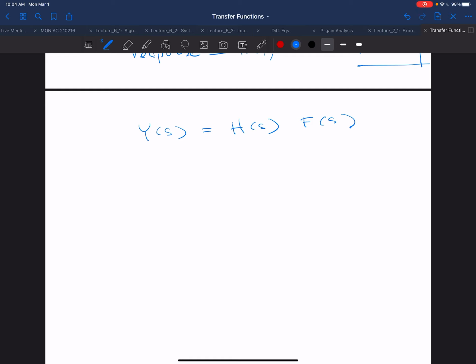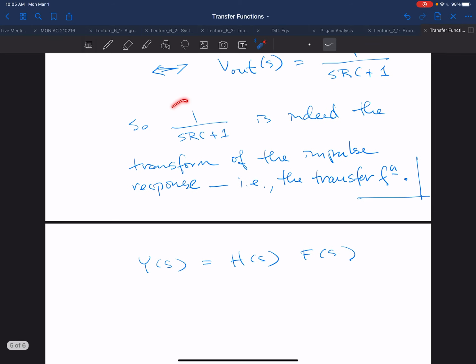So we'll consider the responses to unit impulses and also to unit step functions. And then we'll look at examples of certain transfer functions. By considering just a couple of different examples, we will be able to extrapolate to much more complex transfer functions. This is one example that we're going to look at. This transfer function we call a first order transfer function because the order of the denominator polynomial is 1. The degree of the denominator polynomial is 1. So we call this a first order transfer function, or a first order system.